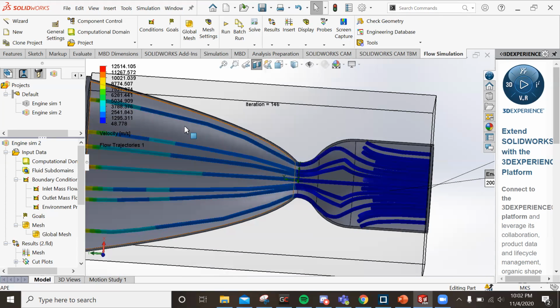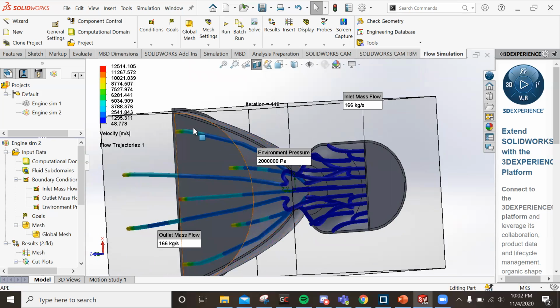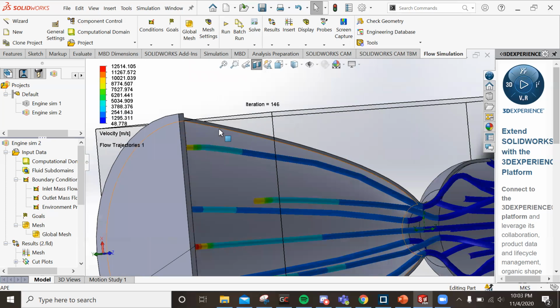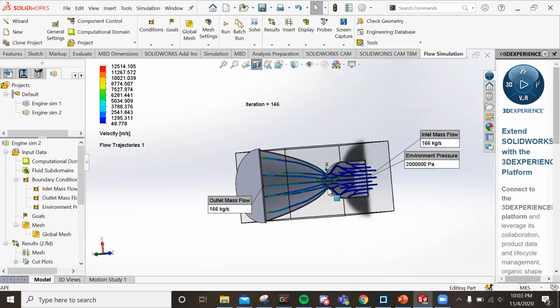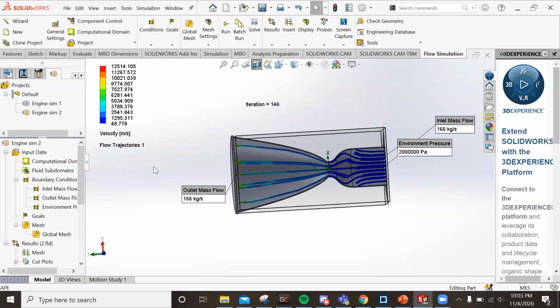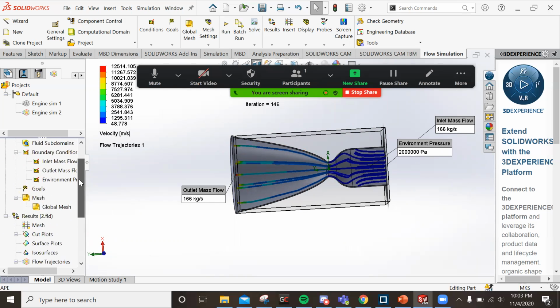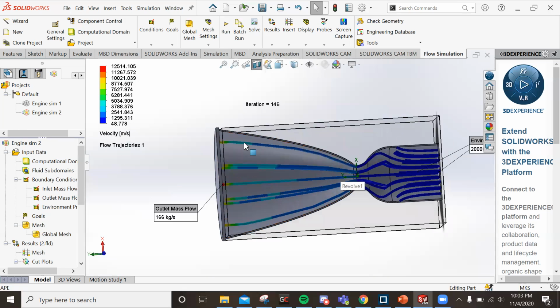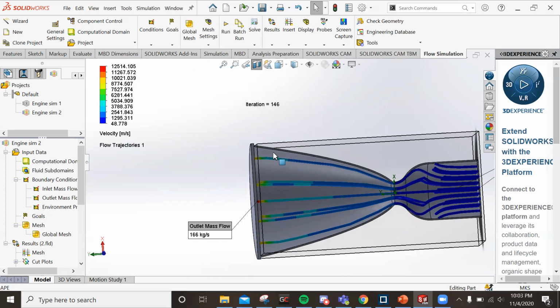So they flow through the nozzle and they look like they follow the nozzle relatively well. If you get flow separation, that's bad. It'll look like it'll follow the nozzle for a while and then just kind of suddenly cut inwards. That's not good, not ideal. So what should they do about it? Oh yeah, if that starts happening, just make the nozzle shorter, just cut it off at where the flow is separating.